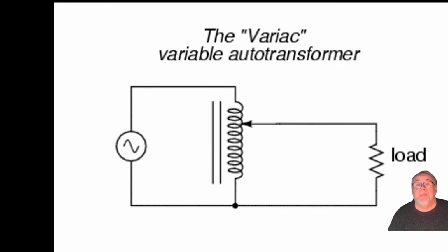So what you've then got to do is put a big fuse in it so it doesn't blow. But if you put the big fuse in, you don't get the protection when it's running, when you've got your equipment on it. So you want to have two fuses on this, basically, one for when it's up and running and one for when you're switching it on. But of course you can't switch between the fuses because that would involve switching, in which case you would blow the fuses. So the trick that I have used on mine is to put a lamp in series with the Variac.